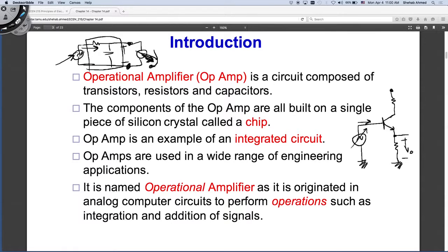If it's high frequency, the capacitor will act like a short circuit, so it will attenuate the signal, and the motor will not see a voltage in that case. So it did provide the logic that we want. But it depended on the fact that this sensor was able to provide enough current and voltage to run the motor, because it's a circuit here.